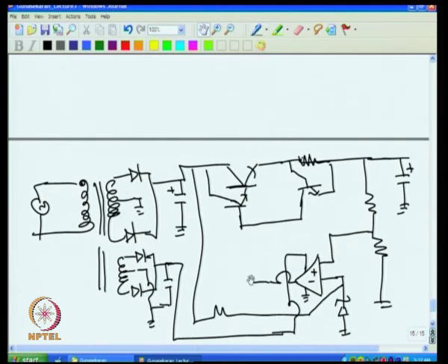Now, we want high voltage. So, what I can do is, I do not give this directly to the output; for example, I can have a transistor arrangement here, then connect this to the collector and put this transistor here and a resistance here. Now, this works as a high voltage regulator. Instead of connecting the output to the base of this transistor, we have connected it through this transistor and resistance arrangement, such that you will get high voltage at this point, and that is transmitted here. Of course, if the voltage goes high, then this goes high, then this will go high, and the current will flow more, and this current also will flow more. So, more current flowing here will reduce the voltage at this point.